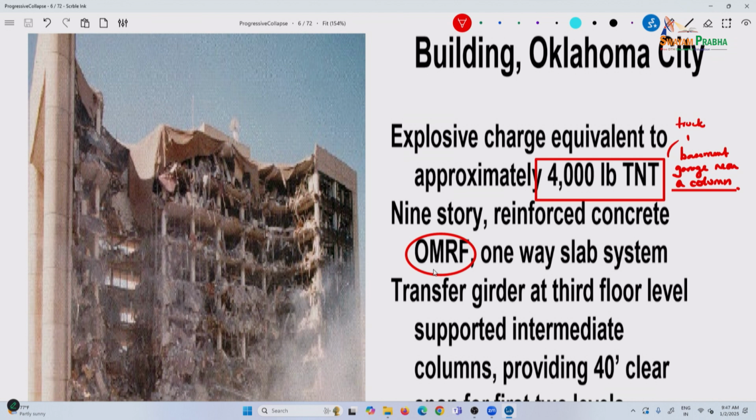You have to provide that, and that is something that even we have looked at in seismic. Let me just take a little aside. In seismic, R goes from even 1, but typically from 2 to 8, and the R value is what is known as the response modification factor. Response reduction factor.